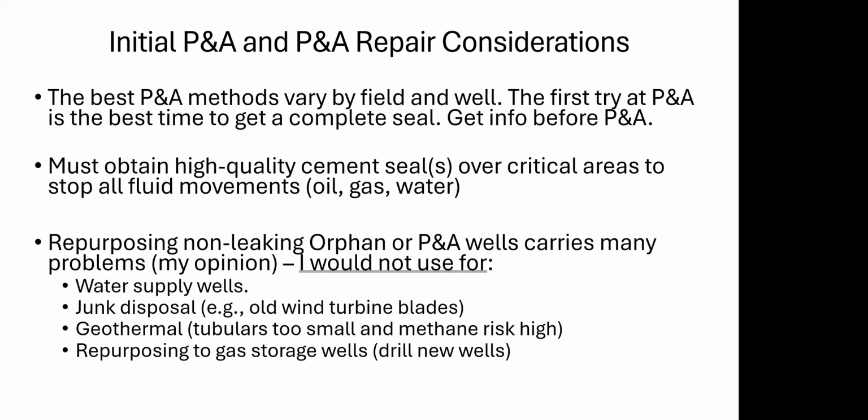and when I was looking through this area of repurposing these wells last week, I found that several sources were suggesting you could use them to store old windmill turbine blades. Please don't do that, because if that well ever starts leaking from the plugs below where all this is stored, you're going to have to pull all of that stuff out to be able to get down to it. So be very cautious about repurposing any well that's been shut in for a long time. It needs tests, it needs to be investigated.